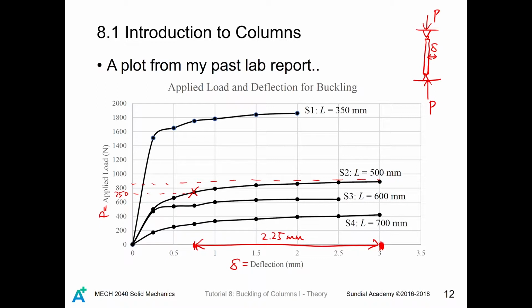And by this trend, you can observe that once the applied load onto a column reaches some extent, then the deflection could increase in a very terrible trend, that once a load is larger than some critical load, the deflection of the column could increase very rapidly, which brings very large danger.